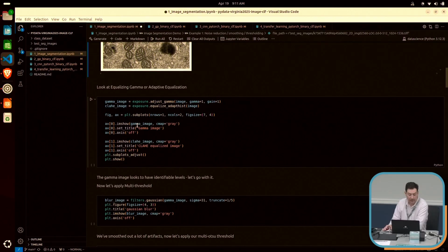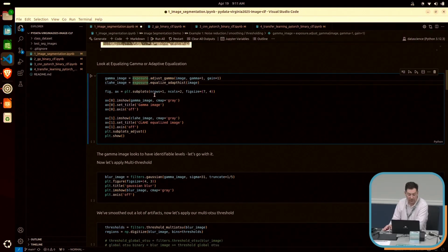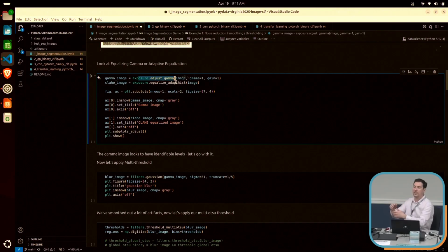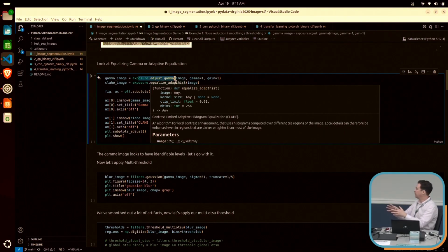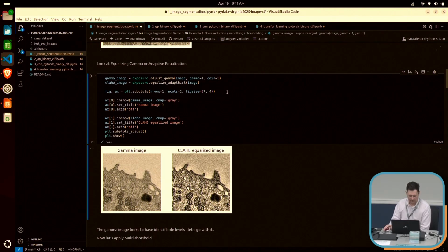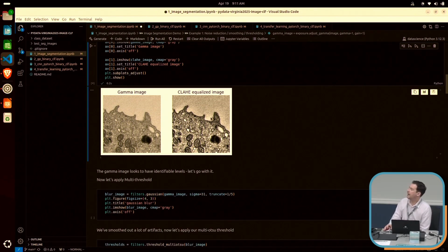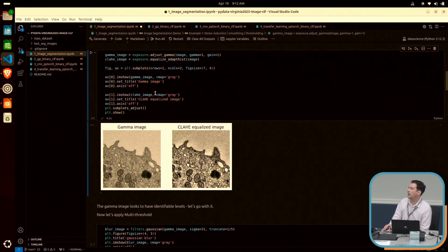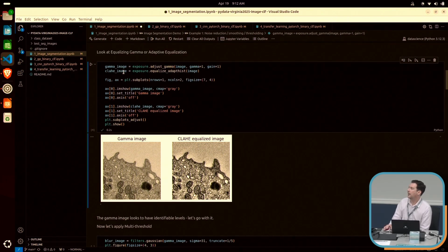Now first let's try to clean up those images we talked about. The first step we want to do is try adjusting the gamma, and then this whole operation you have to tweak the settings to really achieve what you're looking for. So we can run it here, and you can see the gamma. We could have tried the adaptive histogram, but let's go with the gamma cleaning.